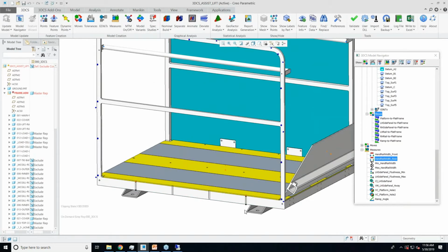Yeah, you could use classic moves for most of the building, and if you needed to check the ramp throughout its range of motion, you could simply put the ramp on with a revolute joint and apply a motion move to that. So you don't have to use mechanical moves for the entire assembly to be able to take advantage of that kinematic simulation function. Mm-hmm. Correct.